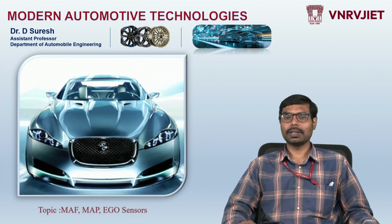management system basically consists of three different segments. One is the input segment, one is the control unit segment, and the third one is the actuator segment, that is the output segment. The input segment comes from various sensors. Based on the sensor inputs, the electronic control unit, the ECU, will analyze the information and provide a proper output to the actuators. So the sensors corresponding to an SI engine management system,